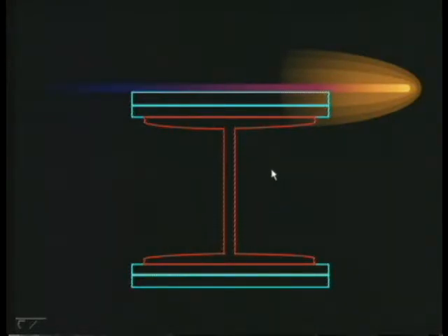See? If your load is much more, a single plate is not sufficient, then take an I section, add 2 plates on either side. These plates offer some section modulus, the I section offers a part of it. So this gives you enough section modulus.